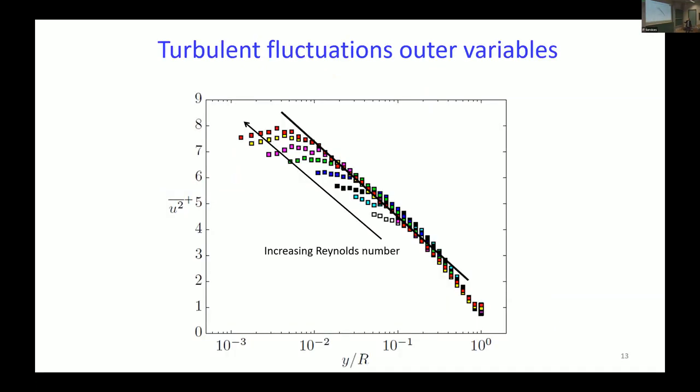And what we could see from this is now the same as shown before, the variances, non-dimensionalized in inner units with u tau and plotted in outer coordinates. We could see here, as the red is the highest Reynolds number, that there was a logarithmic dependence that appeared in the variance profile. And I should point out that this kind of behavior will be highly biased by spatial filtering, right? Because it will be pulling this down, and it would not look like a straight line in this plot, but instead would look like this. So we were able to see this logarithmic behavior, and it was really due to, first, the facility that can allow us to test at 100,000, but also the small sensors.